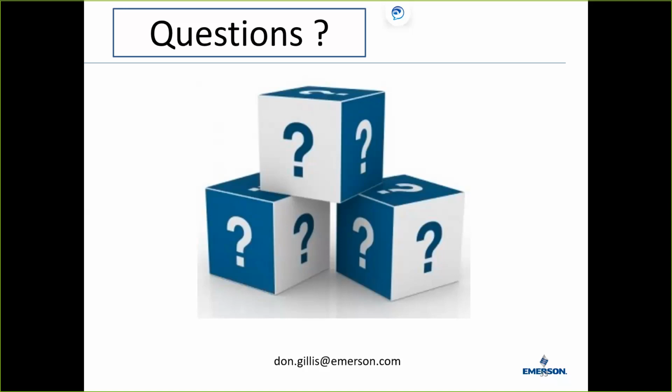Another question we have is, how do you know when to use POE 32 versus POE 68 oil? That's a good one. So that is going to be by design. The designer is going to make that call. You have to look that up on your bulletins. I know that one has to be by application. That would just be by system.